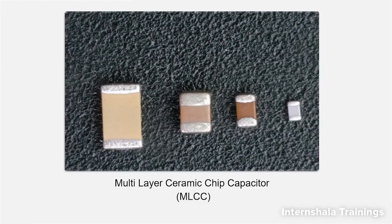Okay, so there are actually two approaches to get the value of the capacitor. The first one is by using the multimeter. The multimeter that you use should have a provision to measure the capacitance of a capacitor. The second method is to use an LCR meter, which is available in the market. Using that, we measure the value of the capacitor. Just by looking at the capacitor, you will not get an idea of its value. You have to use the multimeter or the LCR meter.